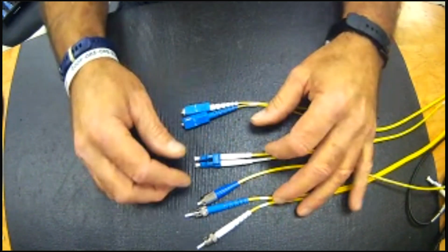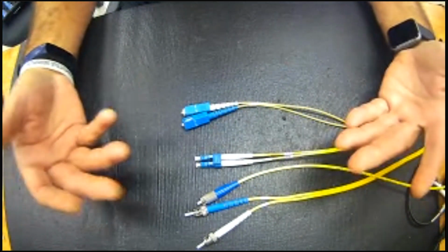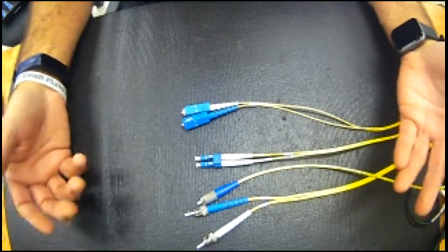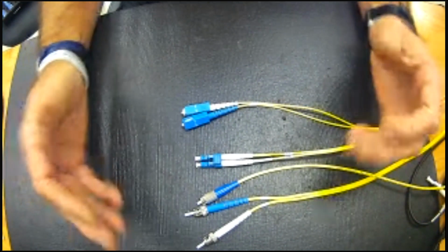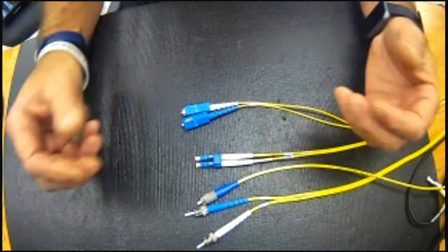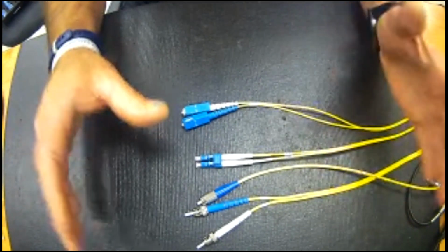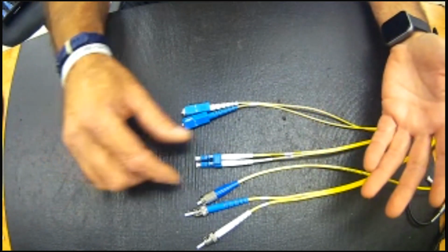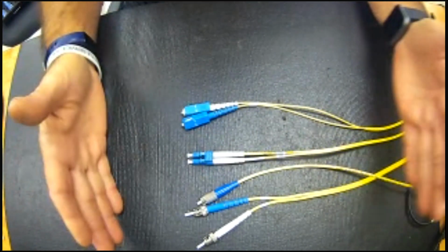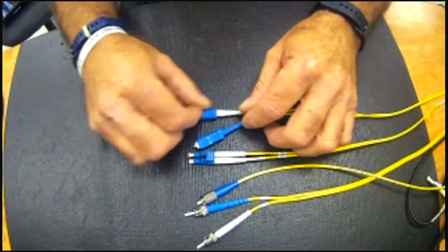If you don't say these phonetically, I'm sorry, but ST, FC, LC, and SC all sound alike to me. SC, FC, and LC pretty much all sound alike. It's imperative that you say these phonetically, and I would suggest you never verbally give that to a purchasing person, that you insist also with them, and they write it out. Because if they order 500 custom-made patch cords with the wrong connector on them, you're going to eat them, and you don't want to do that.